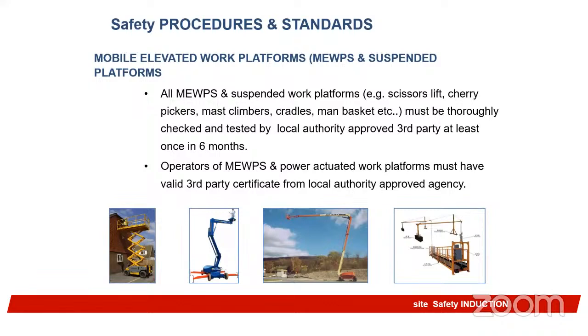When you want to move from one point to another, you should bring down the working platform, move to where you want to go, then move it up again. You shouldn't move your mobile elevated work platform while at that height and start moving from one point to another. It can tilt. So you should look at the ground floor system before you move from one point to another. It should be properly inspected and properly checked at all points in time.